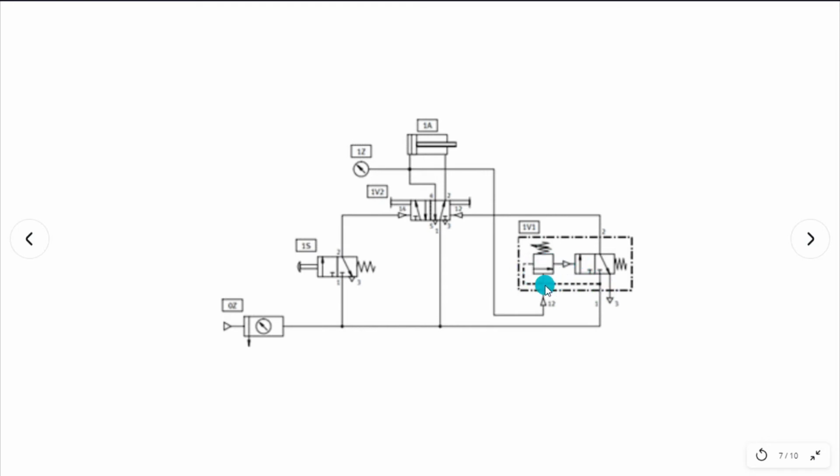And then, when it has enough pressure, it will now push the position of the directional valve inside your sequence valve so that it can let the air pass through from your input going now to your output. And then that output will eventually push back the final control element to its original position, retracting now your cylinder.